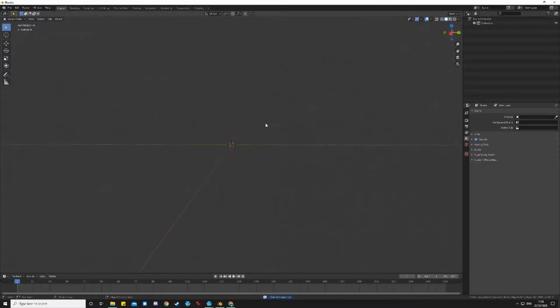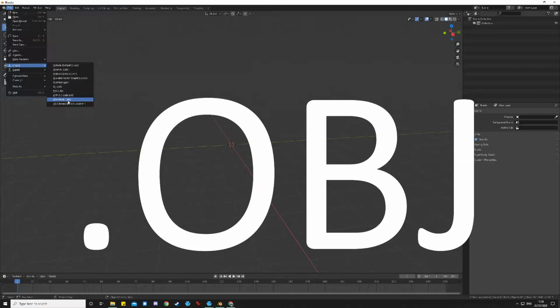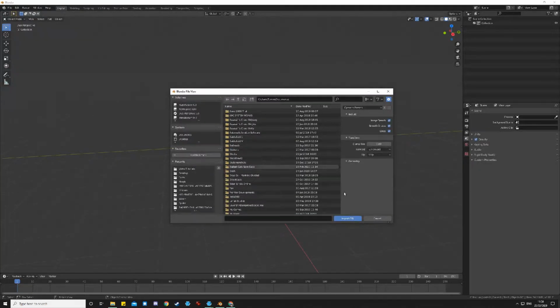Now, Blender's quite a complex program, so I'm not going to be able to explain every single thing in here, but it gives you an idea of the process that I go through in the workshops, taking a plasticine model that someone gives me and how I turn it into an object that works on Tiltbrush. But yeah, the next thing I'll do then is import the object. So the version of the object that we've got from Meshroom is an OBJ. It says Wavefront .obj is the one we want to import, and then I need to find the folder that it's stored in.